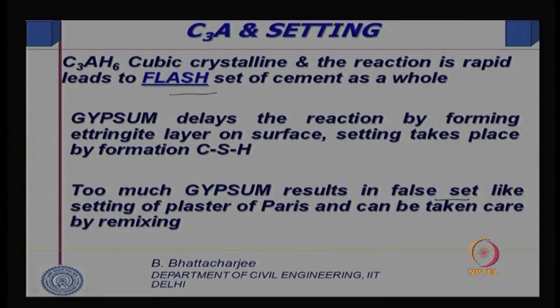Too much gypsum is again not good, because it results in what is known as false set, which sets like plaster of Paris, because gypsum itself will react with water and form hydrated gypsum, like plaster of Paris, and therefore this is also not desirable. This is called false set, but you can actually remix it a little bit and it will set again. So, the optimal quantity of gypsum is important.